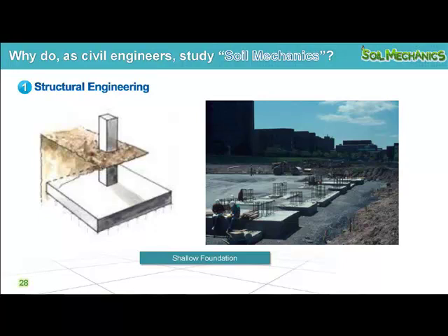Before we decide, we need to know what type of structure will be constructed and the underground soil condition, how weak, how strong. If the subsoil condition is very weak, we must use a deep foundation or pile foundation.